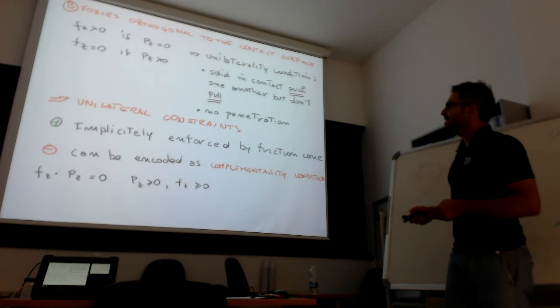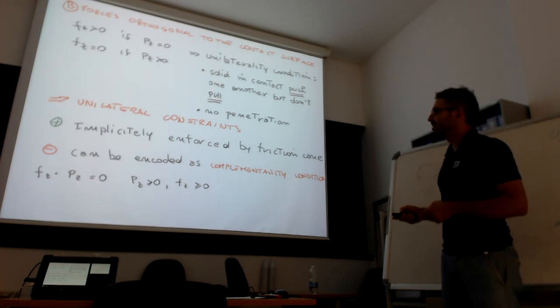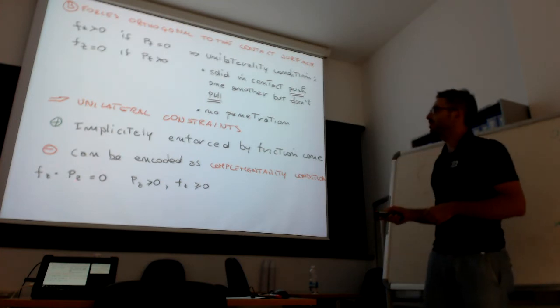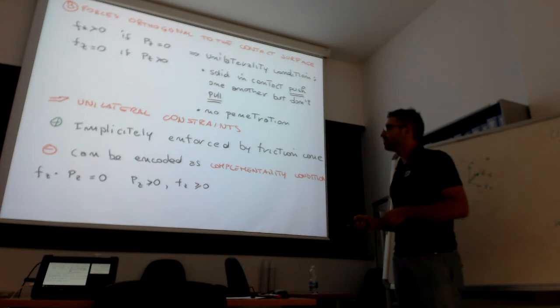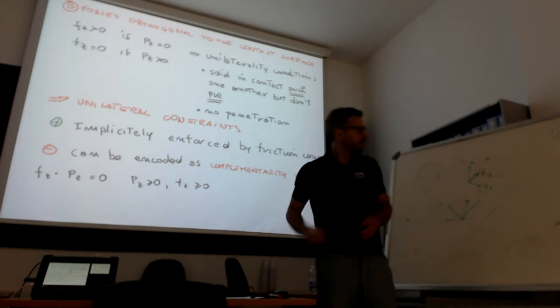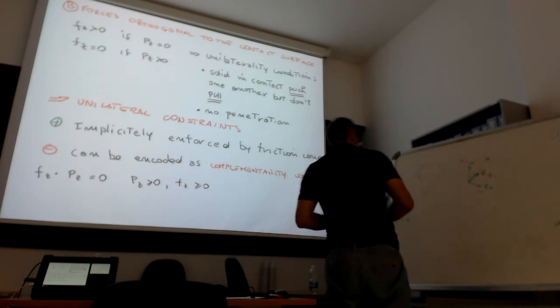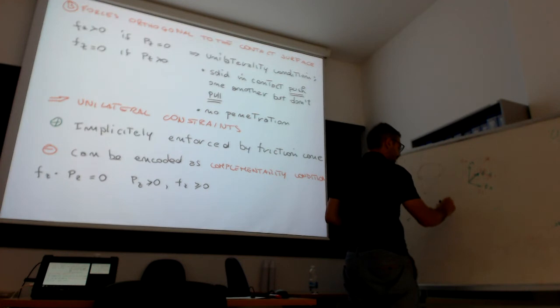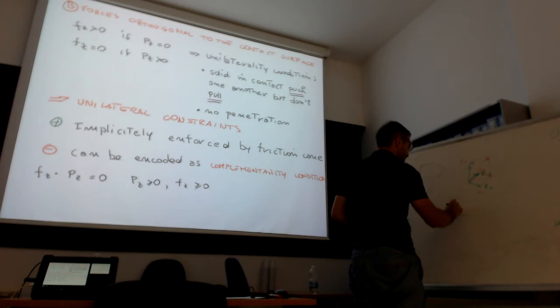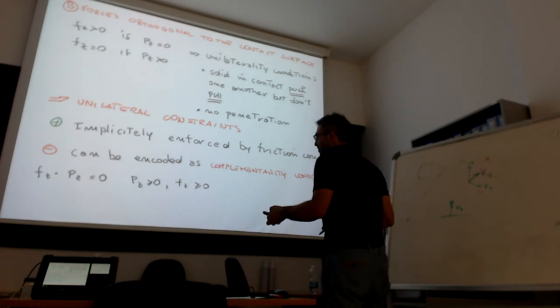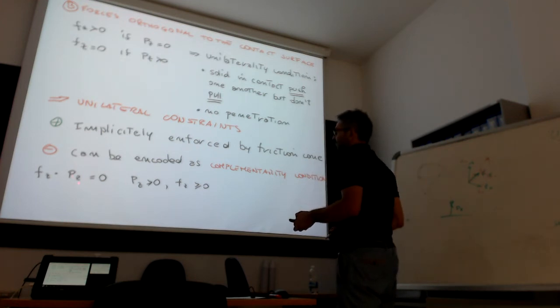You know that the unilateral constraint can also be written as a complementarity constraint, where you have the product between force and contact position to be zero. So this is the contact pz, the contact position, the distance of the end effector from the surface, and whenever this distance becomes zero, then f can be positive.